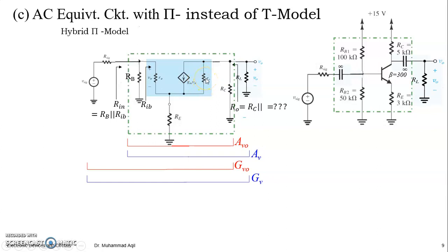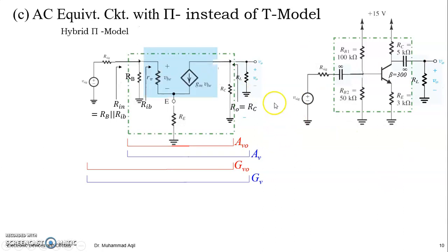So as recommended for the same circuit with RE, it is recommended to neglect this R naught, and it is fair because this R naught is very high. Once it is coming in parallel with something, then that parallel thing will be leading while finding the values, right? So let's neglect the R naught, the early effect.